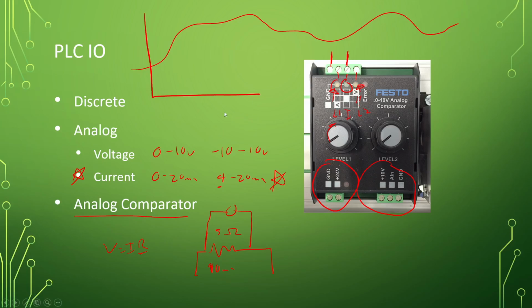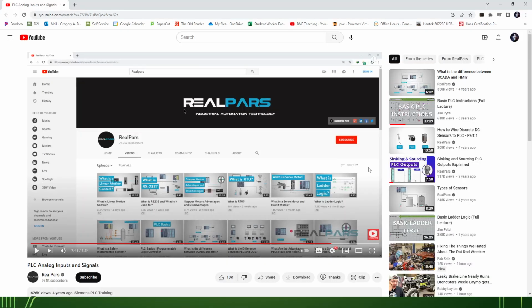All right, we're going to quickly watch a real parts video on analog just to kind of bring it all together for us. So just a quick review of analog. They did get into the thermocouples and whatnot, which are a whole different ballgame. Right? And if you ever do get into thermocouples, make sure you stay consistent with your equipment. So like they said, type J, there's also, I think, type K and a whole bunch of other ones. So if you have a probe that can read type J thermocouple and you put type K in, it's not going to work. So whatever your test equipment can handle, make sure that that's the sensors that you're using. So they have different ranges and different capabilities.